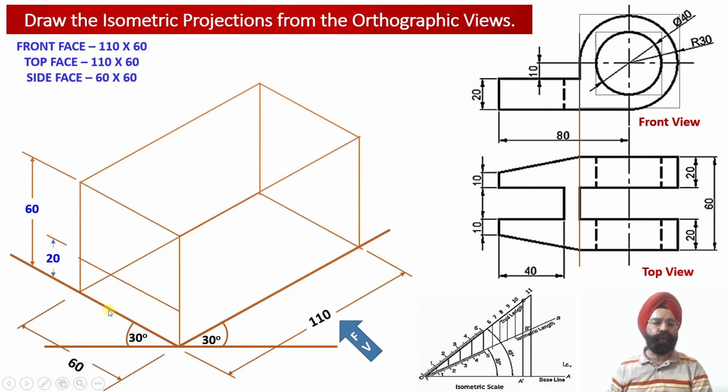isometric x-axis over here. So now we know that corresponding to this horizontal web, again we have got two portions. One portion is this rectangular slot, then we have got a 10 millimeter portion corresponding to this surface area. So now we are going to measure lengths of 40 millimeter and 50 millimeter from the center point. So we have measured a length of 40 millimeter and 50 millimeter over here alongside the isometric z-axis, so that these two end points we are able to locate appropriately in the isometric projections.